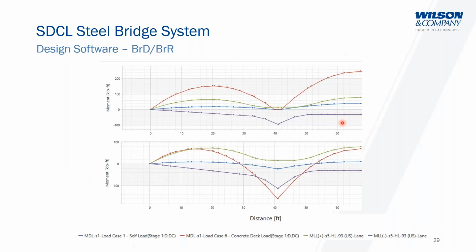You can see the difference obviously really lies with the dead load, as expected, as you have zero moment going across that support. If you just compare the deck load moments, you're looking at 230, 240 kip-feet for the simple situation at midspan, and then that basically becomes a negative moment transferring over that way. So it's a pretty neat system. You just have to size your beams a little bit differently, but you can see how that load really transfers based on the concept here.